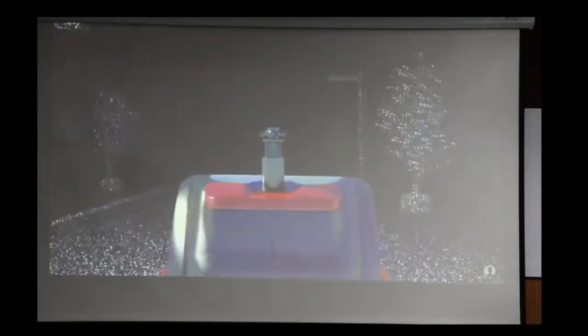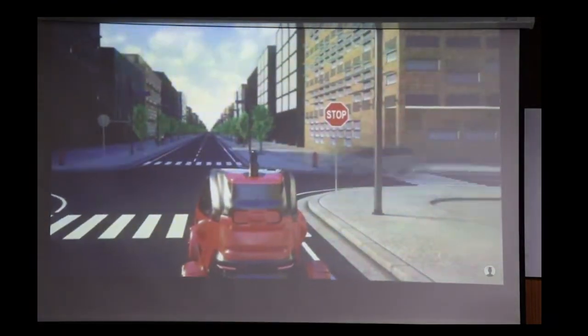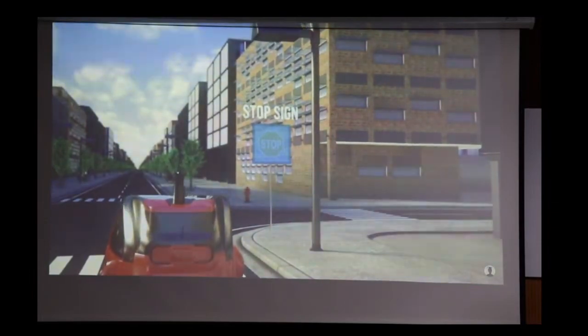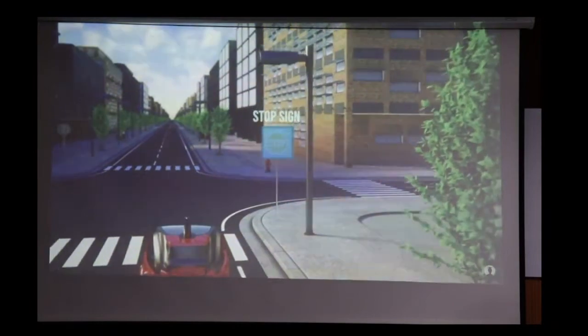LiDAR is a key component in many vehicles. LiDAR works similar to radar. LiDAR, however, does not use radio waves, but many light rays that are reflected by the objects in the surroundings and detected by the LiDAR sensor. In this way, a point cloud is generated from the environment. However, LiDAR does not recognize road signs. Cameras use artificial intelligence to recognize and interpret street signs. Cameras are also used to detect obstacles and are needed for lane keeping.